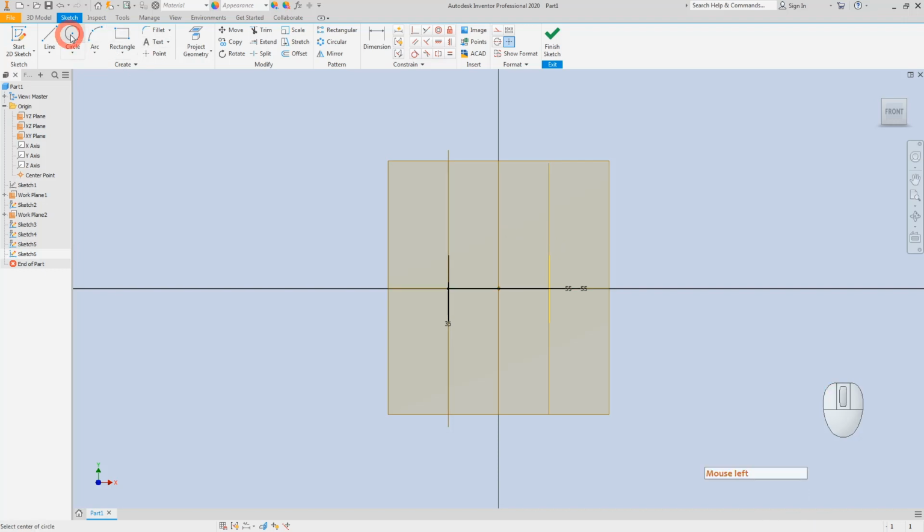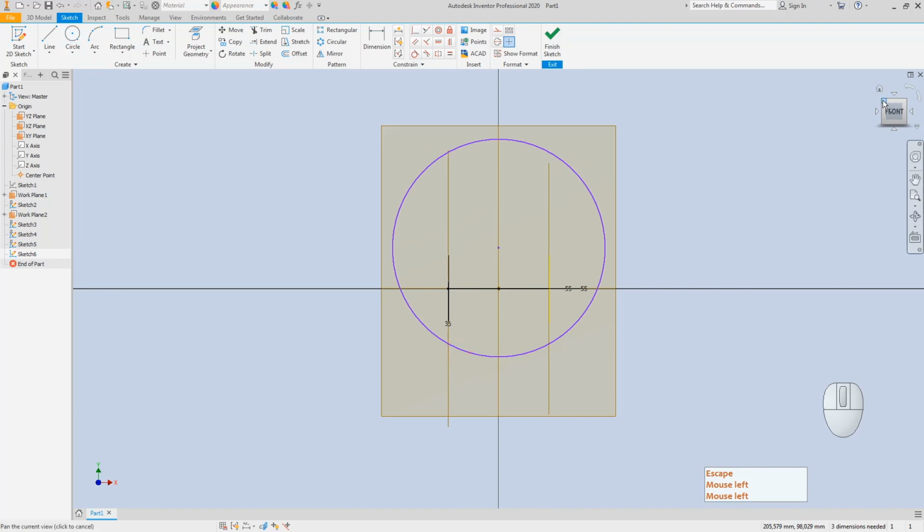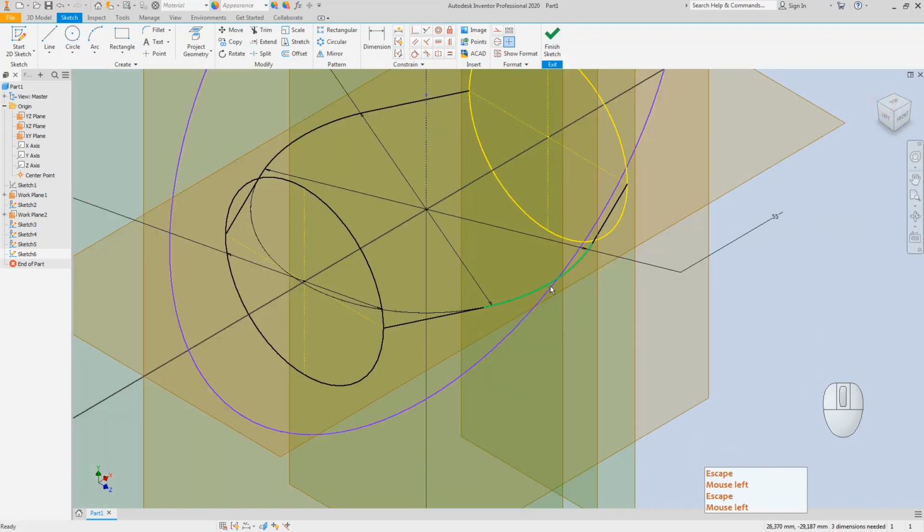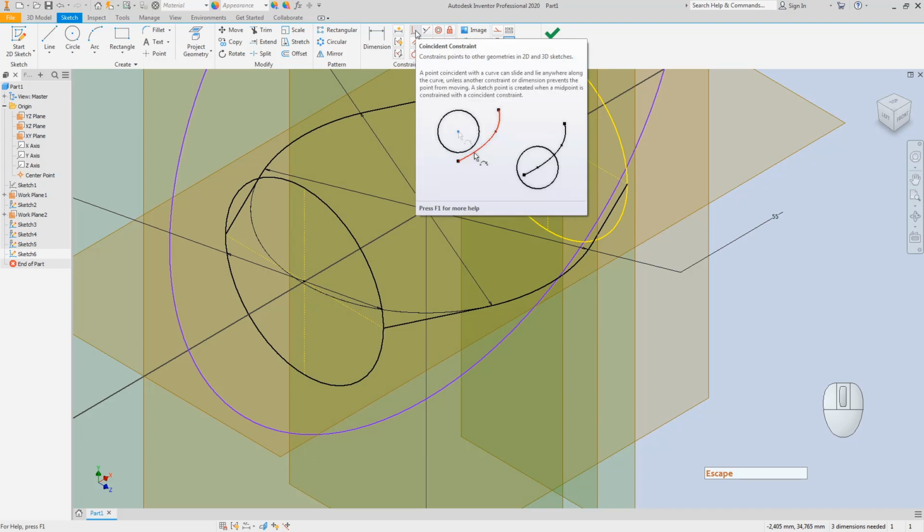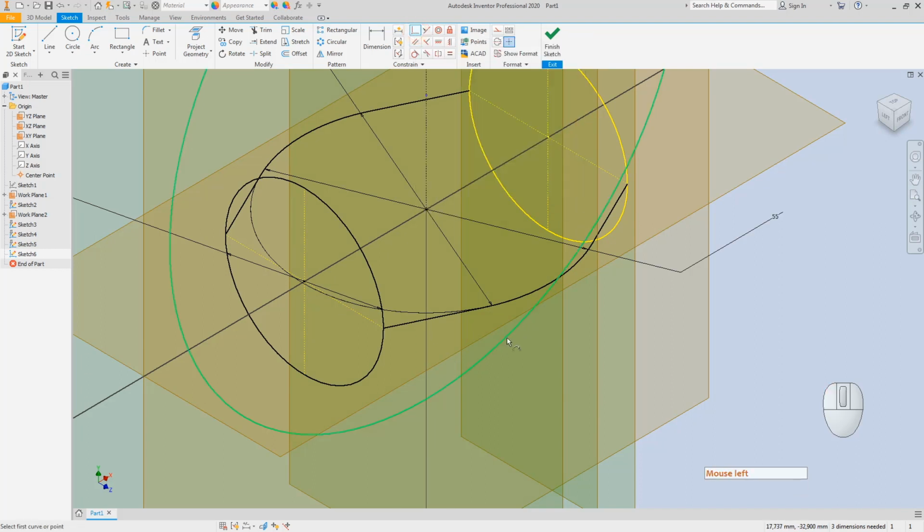For this arc piece, we create a circle on this line, and we will just make the trims to get an arc piece. We will create a relationship between this circle and the project geometries which we have just received from the circles and sections.